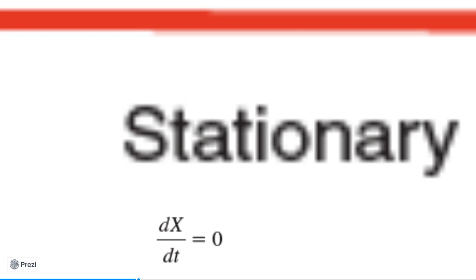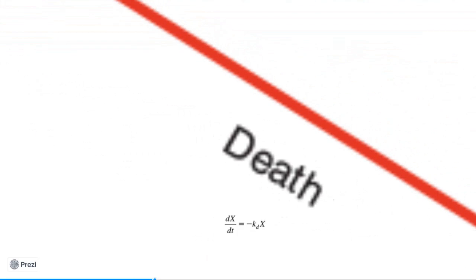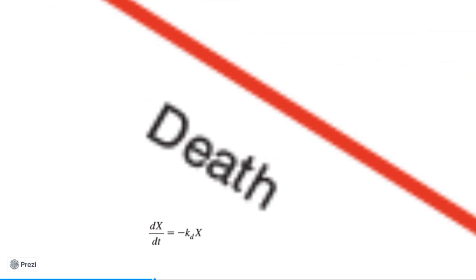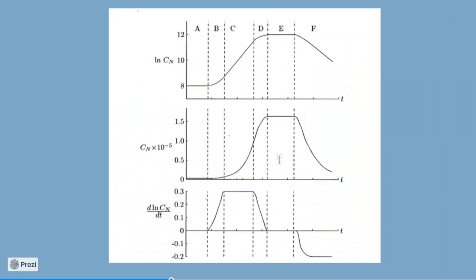the growth rate of the organism is 0, that is, there won't be any change in biomass concentration during the stationary phase. The stationary phase is further followed by the dead phase, where the decrease in biomass concentration is proportional to the initial biomass concentration and is guided by the specific death rate constant. The growth rate of the organism in the batch system of cultivation can be easily understood by plotting different graphs in terms of logarithmic values and change in concentration of cells.